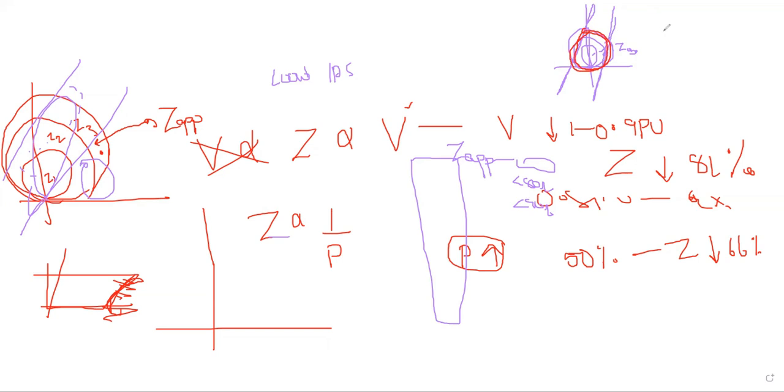Sudden changes in the generator, sudden changes in the voltage, load fluctuation. Okay, there will be sudden changes in the generator. Automatically the load will change and the voltage will also differ. So automatically with that voltage and current, the impedance will change. When this impedance changes, it will come under the zone actually. So if it is coming inside the zone, automatically the relay will operate. Correct. But how will that relay identify this is not a real fault and should block?